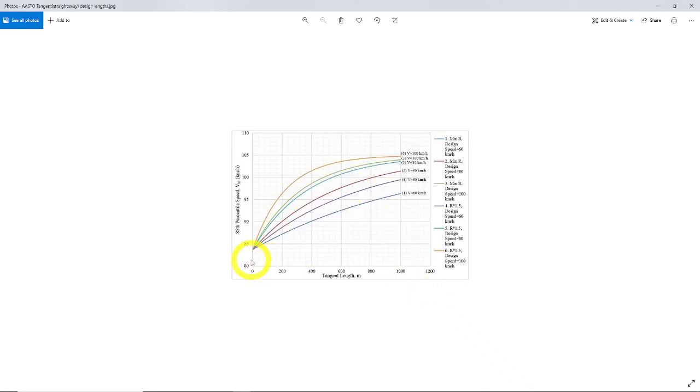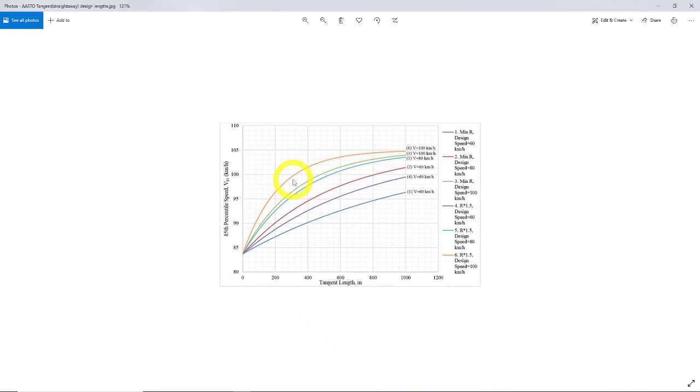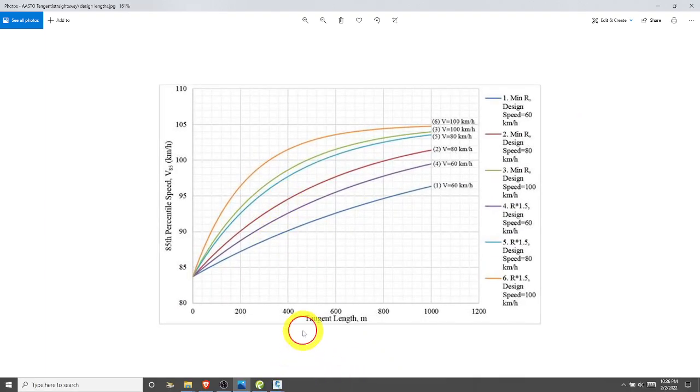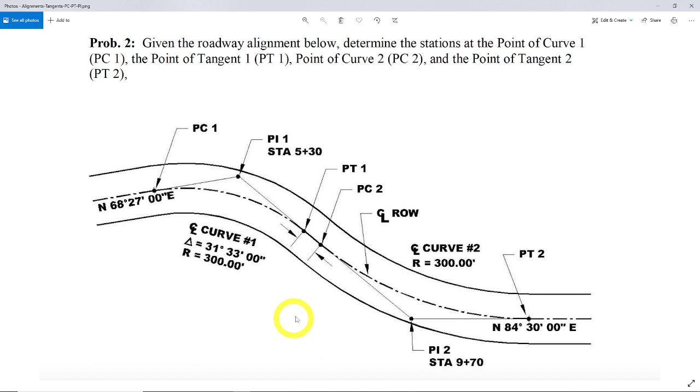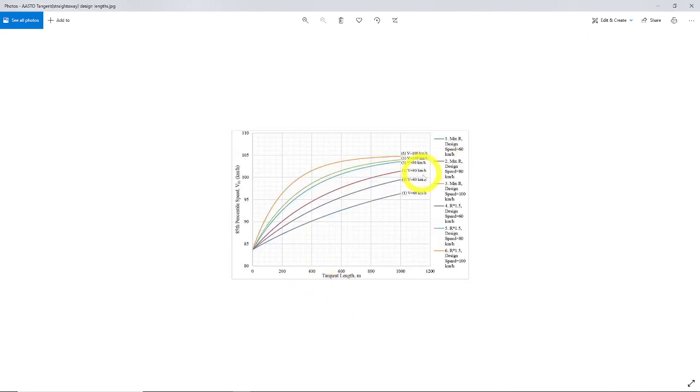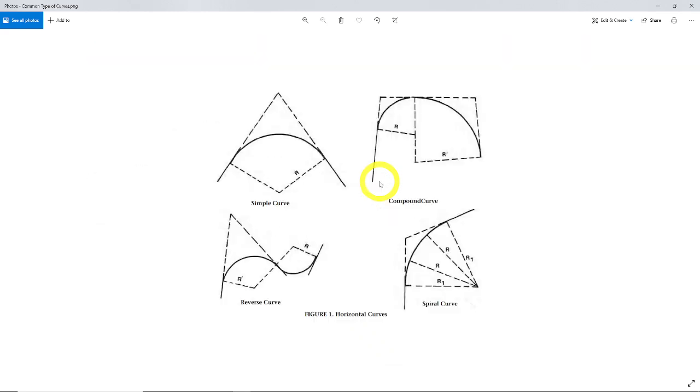This is a higher number in stationing. This is for later. We're going to talk about highway speeds related to tangent lengths. So basically, the faster the highway, the more tangent you might need in between curves. And the faster the highway, the larger the curves you will need. So Interstate 90, their minimum curve radiuses to the center are well over 1,000 in most cases, if not several thousand. They need a long gradual curve, big curve, so you don't fly off the road corner. So we'll talk about a little bit of that, and they need long tangents in between curves. They can't just have situations like this on super fast highways.